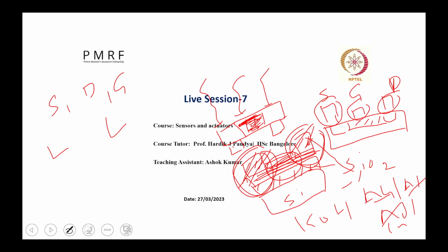Si is very low cost and present in the environment in abundant quantity. Silicon is manufactured from sandstone, sand. So it is available in large amounts on the earth. That's why it is very low cost and easy to manufacture. In my first and second videos, and in week 3 or week 4, I explained how the silicon wafer is identified as p-type and how it is fabricated, the CZ method, and that we can now manufacture 18-inch diameter silicon wafers.